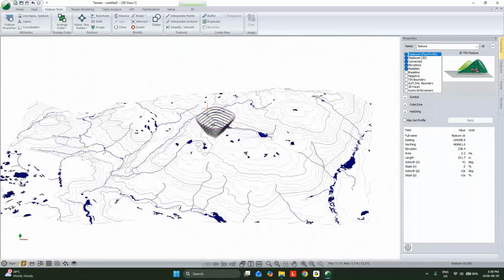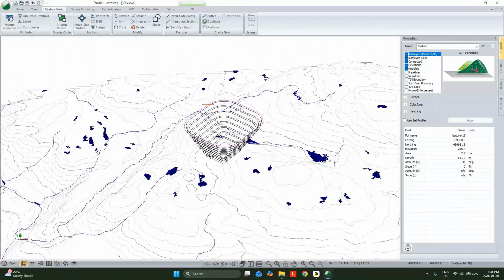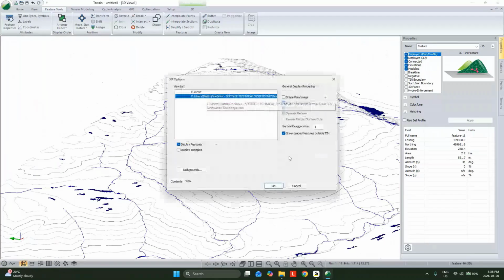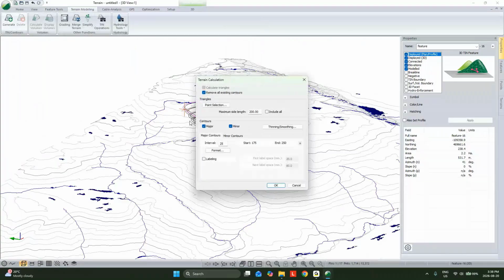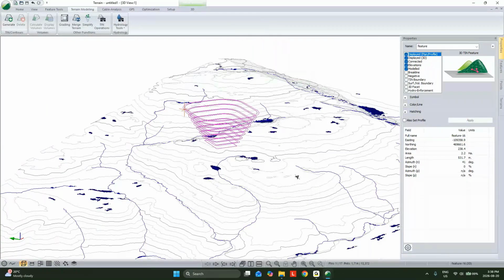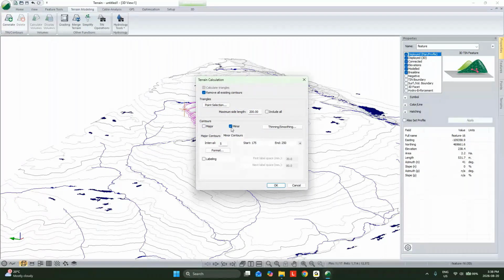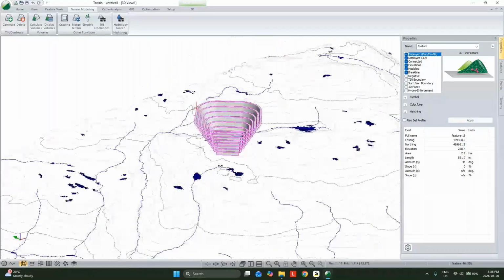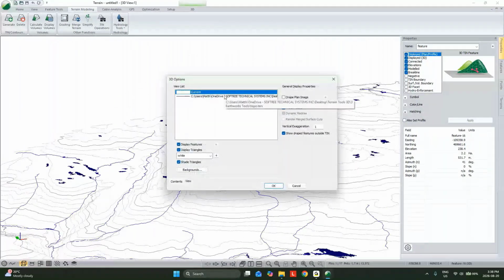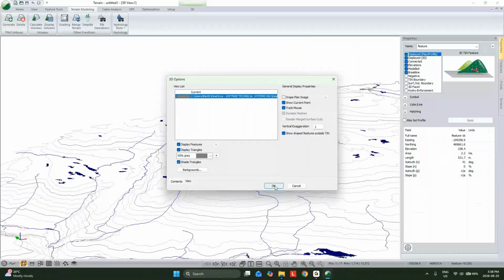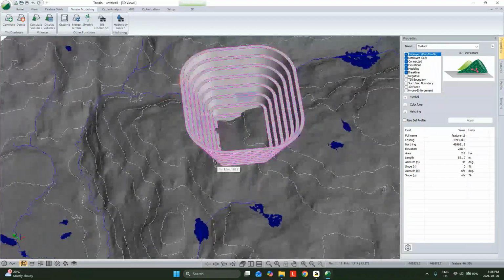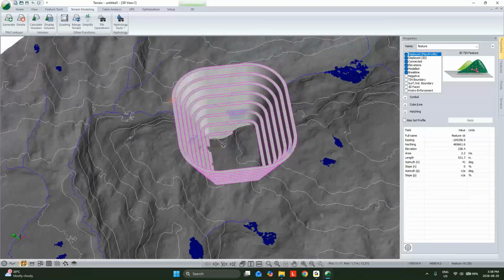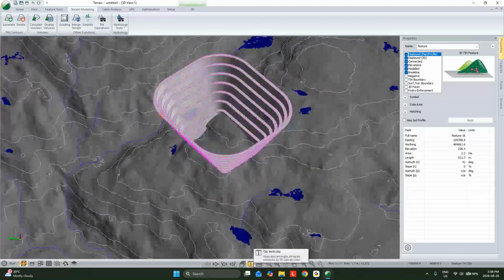Now, what does this look like here? And again, I'll just make it so we can see both of those surfaces. Well, I'll make a surface first. Oops. And they should be break lines for this. So we're going to make our design surface. So it goes way up, probably beyond what we intended to. We've got this other surface. So we don't want to have kind of filling into the sky. So, well, how do we trim this, kind of lop it back to where it should be?